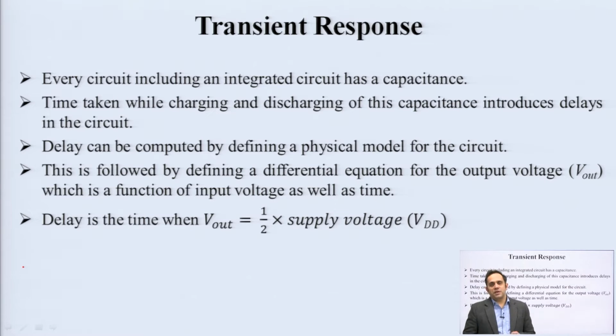Okay. Specifically with reference to VLSI circuits, where you have high density integrated circuits, where a lot of logic is connected or diffused on a small piece of silicon in a very small area and connected with a piece of wire, a very important parameter associated with these ICs is the capacitance. Okay. We have seen in earlier lectures that this capacitance can be the diffusion capacitance between two doped layers in an IC, or it can be the capacitance between a wire and the ground plane, or a fringe capacitance between two neighboring wires. Right.